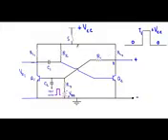Now let me describe the operation of this monostable multivibrator circuit. Here we have used two transistors Q1 and Q2, and I am taking the output across the collector and emitter terminal of the transistor Q2. Therefore this will be our Vout, or output voltage. The collector load of the transistor Q1 is RL1 and the collector load of transistor Q2 is RL2, and you'll see that the collector of the transistor Q1 is connected with the base of the transistor Q2 through a capacitor C1, and the base of the transistor Q1 is connected with the collector of the transistor Q2 with the resistor R1.